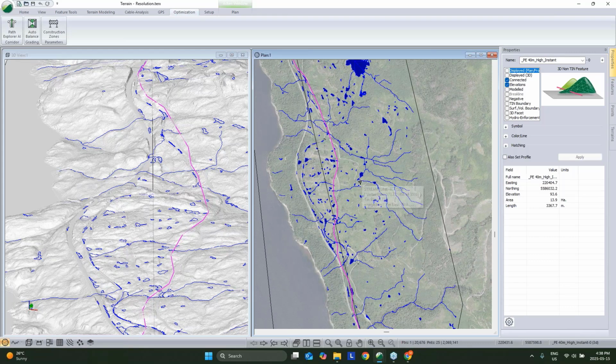That being said, as we consider it from a large project standpoint, using a reduced resolution to figure out at a high level, okay, I want to be in this valley, you can run really low resolution and then hem in an area of interest and run a higher resolution on that area of interest to get a better solution. So that's enough of me clicking around in the software, introducing the idea of tackling long roads and some of the considerations between accuracy and speed.